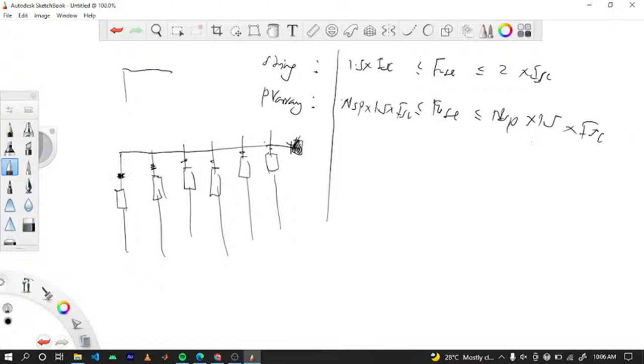Because I provided protection here, but each of these currents will come and flow through a single line here, right? The current here is given by the number of strings in parallel, which is 6, times the short circuit current, times 1.5. This 1.5 is a fixed multiplying factor.